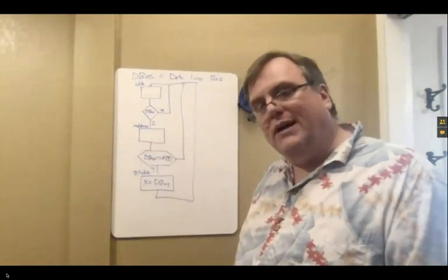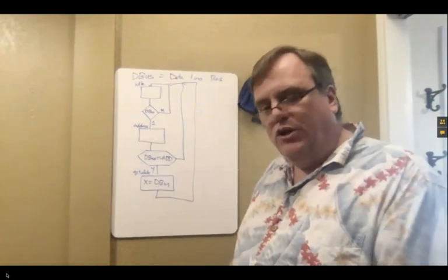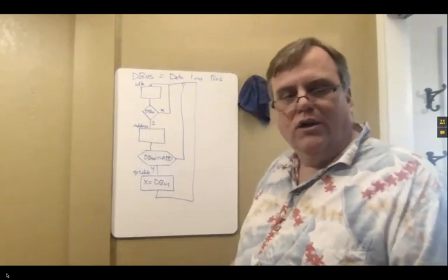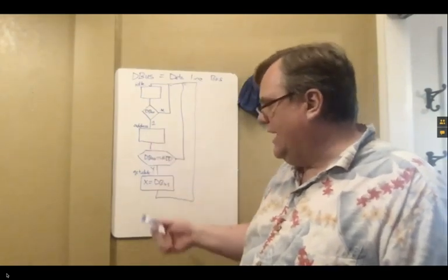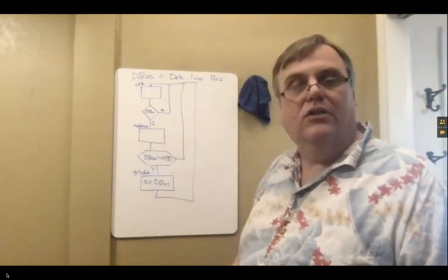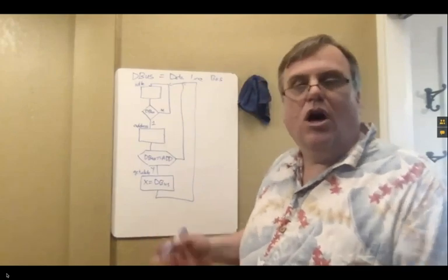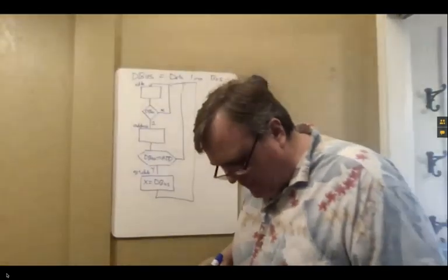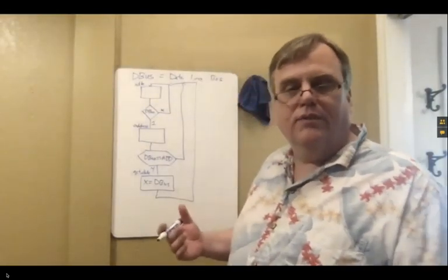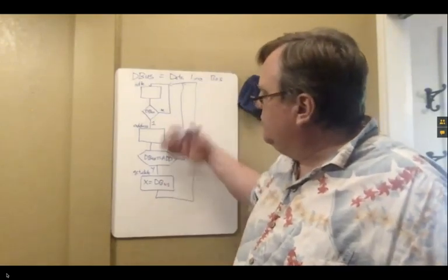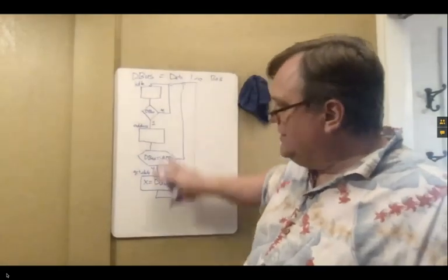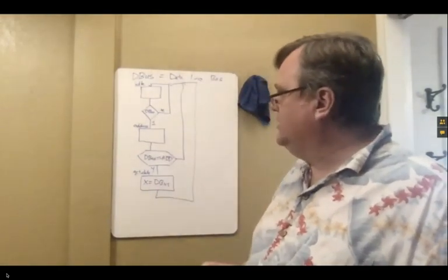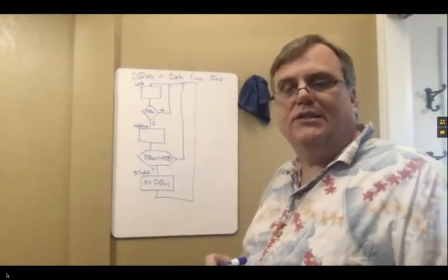For slower buses, like USB or I2C or things of that sort, we tend to send the address and send the data on the same data line, because their speed is not as important, but the number of wires becomes more important. So for a simple design, it's pretty easy to go. Does that make sense?